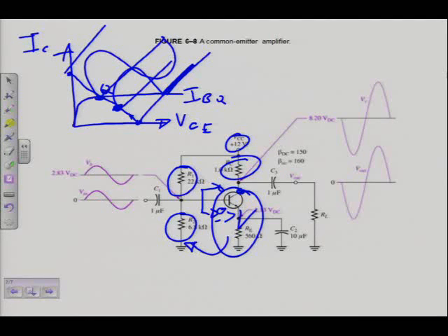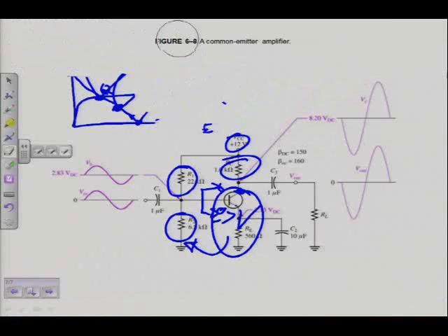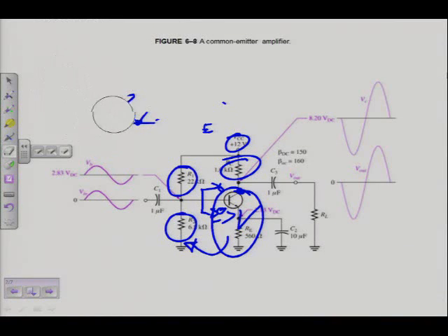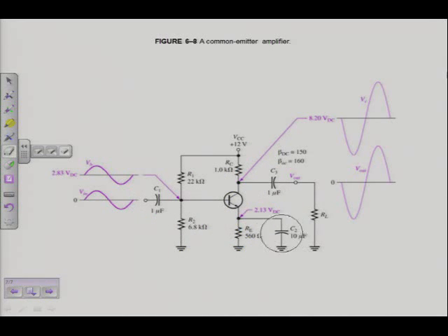What also is important, which I didn't mention here, is actually the very first thing that you should do. Let me just take this off again. Fortunately it's very simple. It's no problem if I only show it to you now. When I start doing my DC analysis, before I do any calculations actually, I have to draw the DC equivalent circuit.